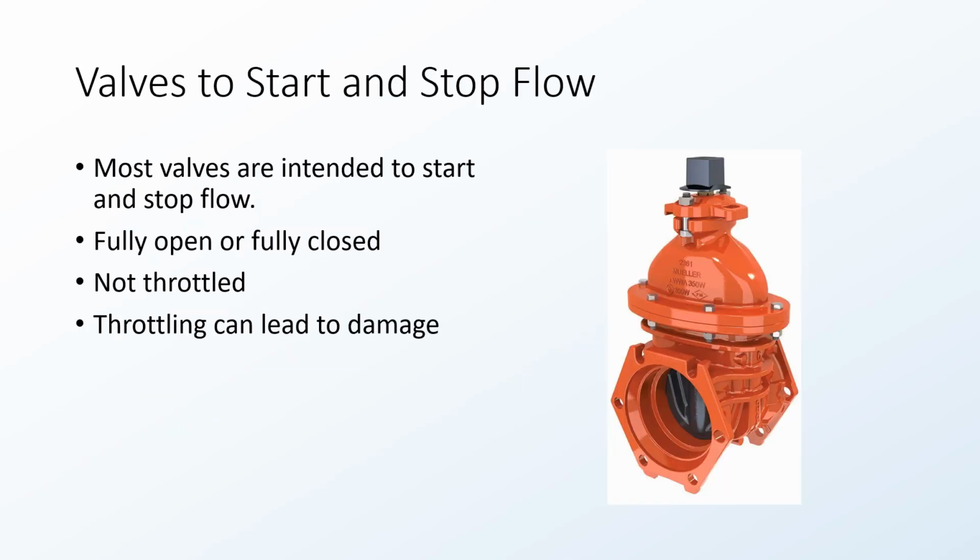So valves are primarily to start and stop flow. Most are intended to start and stop, and they need to be in either the fully open or fully closed position, especially when you're dealing with a gate valve. You have this disc that's inside of there, and that right there is not designed to throttle the flow in a long-term status.